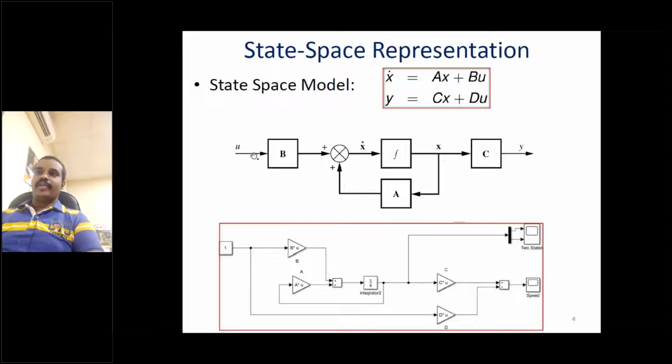It is not dependent on any kind of feedback mechanism. It is not coming from here. So u is independent of any states. You are just giving some input and seeing what is happening. This is called open loop control. This whole thing that you are seeing here is called a system, with input u and output y. So this is a kind of open loop system.